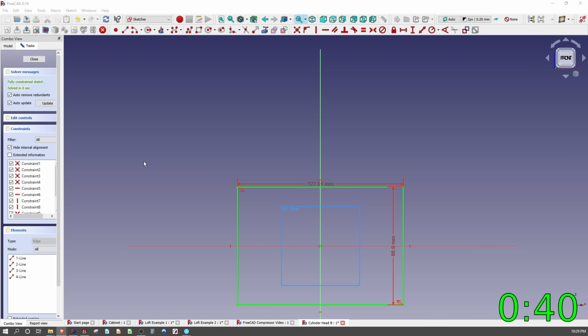Alright, so we've had a little bit of time to think about the change that we made in the sketch. Now, to be fair, FreeCAD also allows you to skip recomputes on things, so you can skip that little intermediate time period and then recompute later if that's beneficial to editing, because if I were to edit this dimension, we'd wait the same amount of time for that to update.